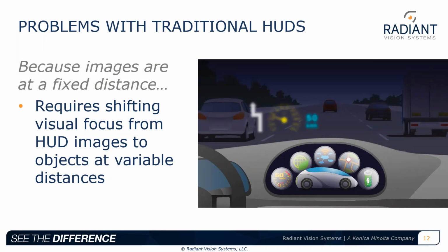Head-up displays are used to create a safer environment for drivers. And if we look at the existing technology for conventional head-up displays, there are still some problems with it. Where the information is being projected at a fixed distance, the driver's not actually able to interact with or perceive the information of the surrounding environment, which means they are looking at the information, let's say, of the speedometer while they're driving, but they're also having to peer and look around within their field of view at the rest of the information on the exterior of the car. This limits their response time from shifting from looking at the head-up display to the environment that they're driving within.